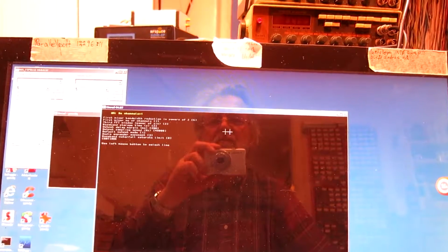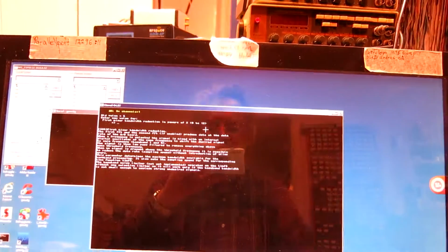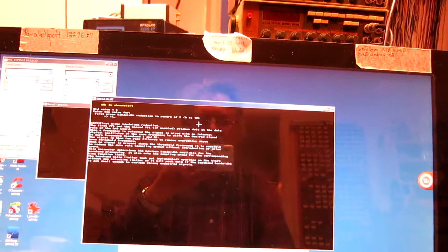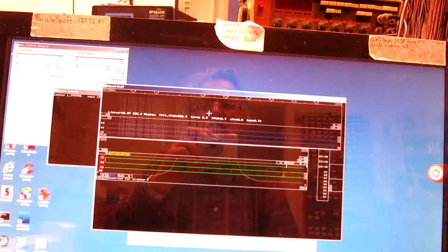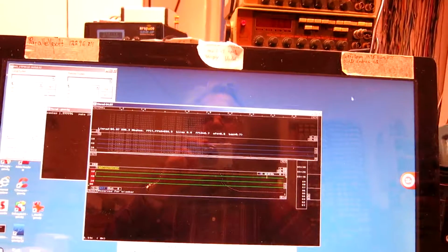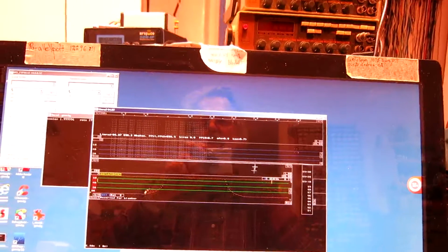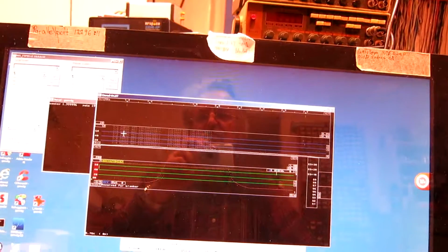First mixer bandwidth reduction, I make it 11 to make it reasonably easy to find small errors in the frequency. So I click on the low frequency here now, 1.2, and I click in the baseband to move it.